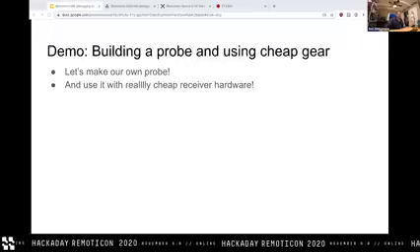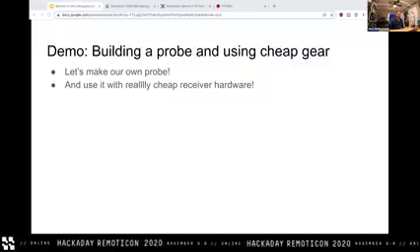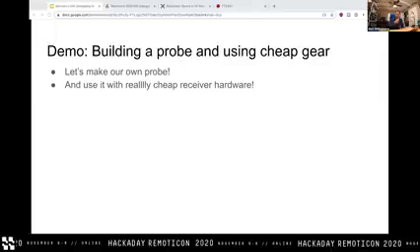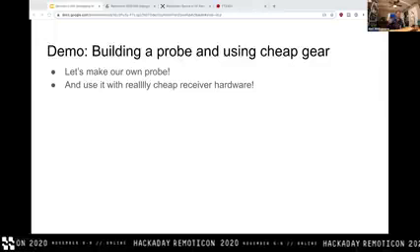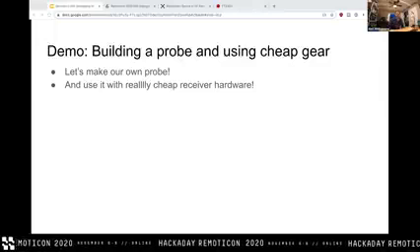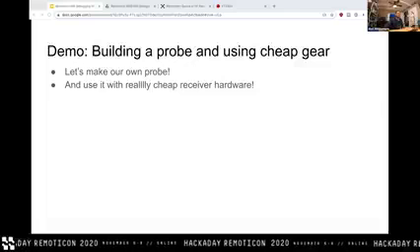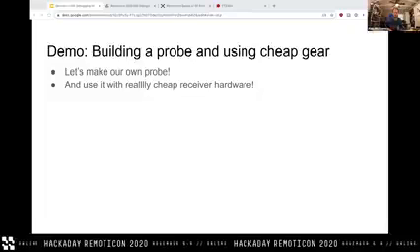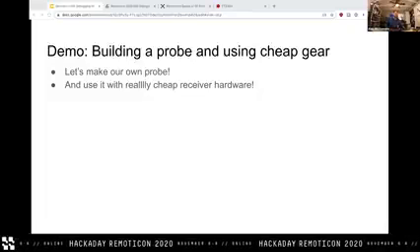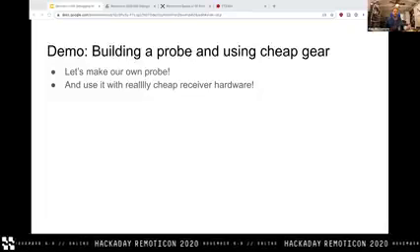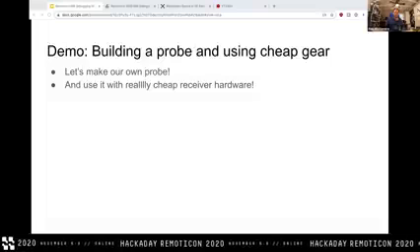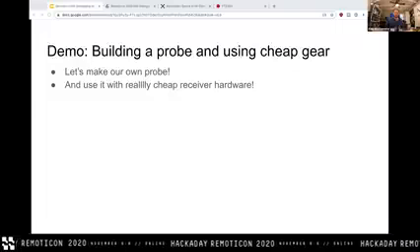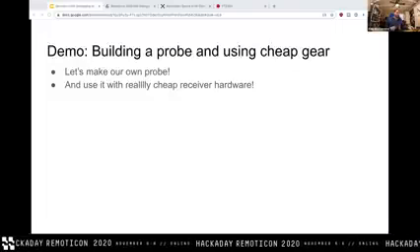Because it's not necessarily enough to simply wave your magic wand over. So in that design, it was the LAN 9512, right? The LAN 9512 was radiating all of this 250 megahertz noise. It's not enough to just wave your magic wand over the LAN 9512 and say, huh, it's the LAN 9512 making 250 megahertz. There's no thing in the data sheet for that part that says, this part will radiate 250 megahertz like a banshee off of this pin, figure it out. They don't offer you that kind of guidance.